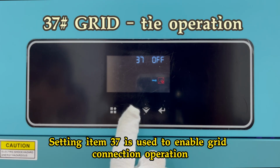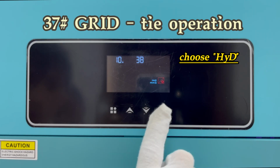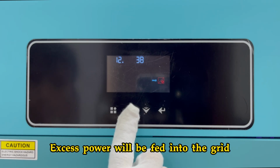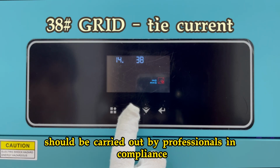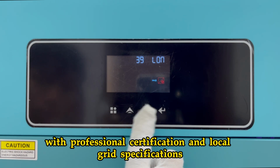Setting item 37 is used to enable grid connection operation. It is set to OFF by default, indicating off-grid status. If you choose HYD, the solar energy will supply power to the load first and charge the battery. Excess power will be fed into the grid. Setting item 38 is used to set the grid current. This should be carried out by professionals in compliance with professional certification and local grid specifications.